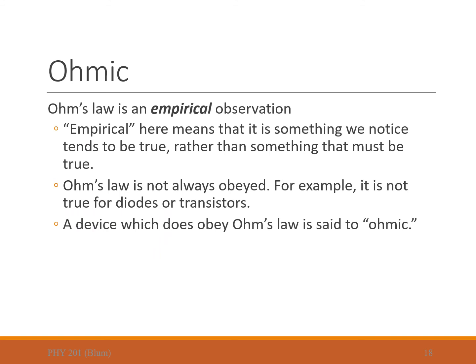So we have to be careful with this word law within Ohm's law. It's not something that's always true. Ohm's law is an empirical observation. We will take a material, apply voltages to it, and see if the current corresponding to those voltages gives us a nice proportionality. Then that material will obey Ohm's law, and we will call it ohmic. But this law, again, be careful about the word law, is not always true. Diodes and transistors, for instance, will not be ohmic. They do not obey Ohm's law.